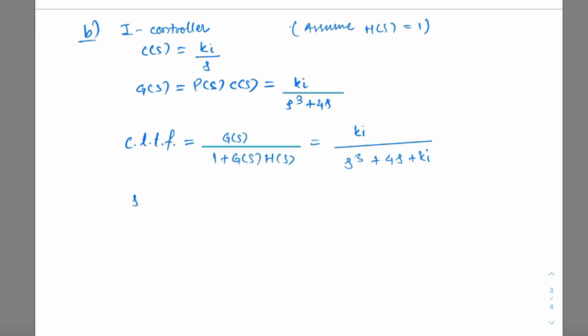This is called a controller parameter space, where the controller's parameters Kp and Kd in this particular case form the axes, and a portion of this space corresponds to the region where the closed loop transfer function is stable. So this is an extremely important and powerful tool.